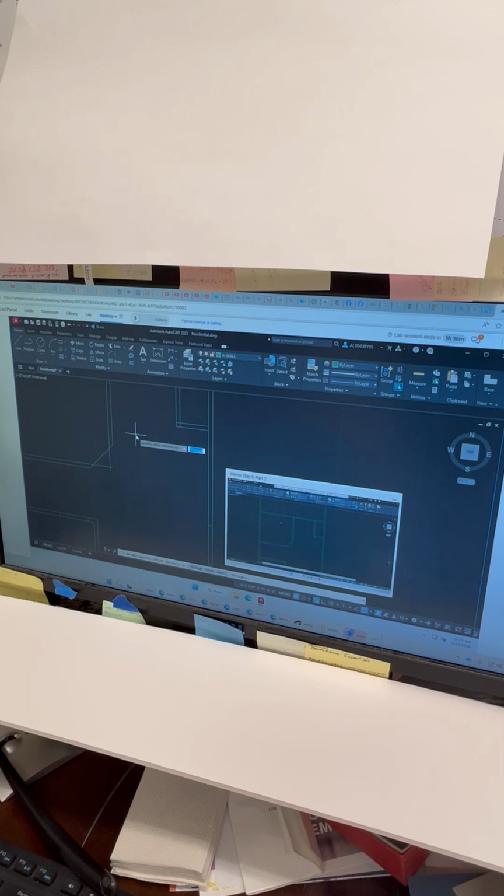I got to go ahead and start the chamfer command. Oh, yeah, you have. Go ahead and hit enter to accept. See, you have to follow the prompts. Look at the prompt at your cursor. It's saying specify the second one. It's waiting for you to hit enter to accept that 2 foot dimension. Just hit enter.